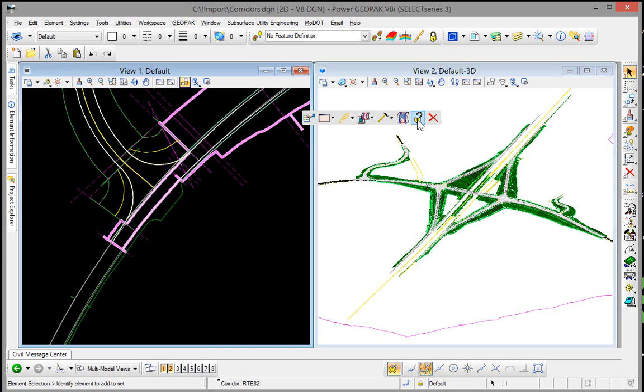After that lock is turned back on, the next command that is done to that corridor will force that change, plus all the other changes that it queued up into memory, to be processed. So the rule lock and unlock activation is a very powerful way to hold off any processing until you have all of the changes incorporated that you want to make. Then you can activate your rule, and that will in turn process the corridor. Every corridor will have its own activate and deactivate option.